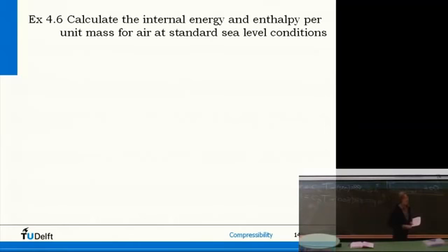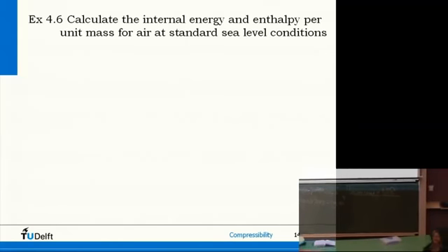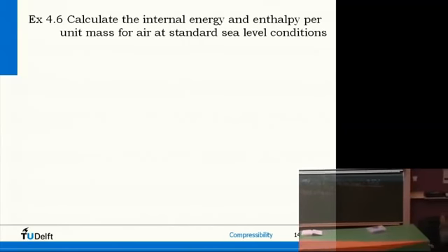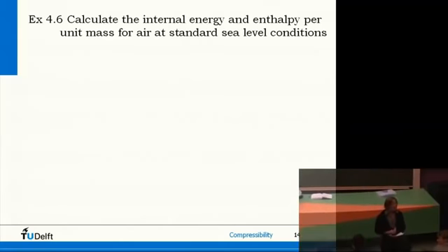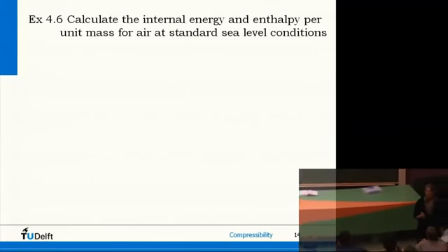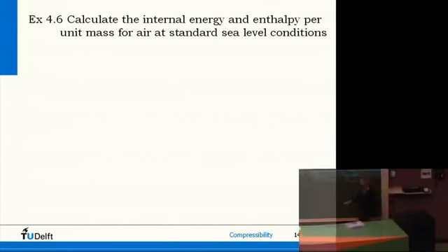And what is the dimension? So we do find the internal energy, CV times T, CV 720, temperature indeed 288, so we find 2.07 times 10 to the power 5, what? Yes? Yeah. Joule per kilogram. Kelvin? Joule per kilogram. Thanks. Because this is energy per unit mass, right?